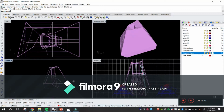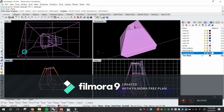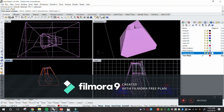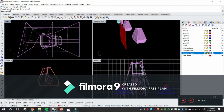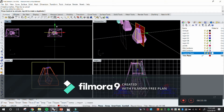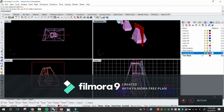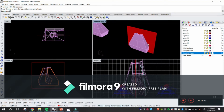Why do I want to do that? Because I want to come back into my front view and draw a plane. Rather than doing surface from 3 or 4 points, there's this one right here, rectangular plane, corner to corner. So I can draw that. Now it's in the front. What happens if I select it and move it? Try to find that half point right there. It's actually going to help us trim this out.